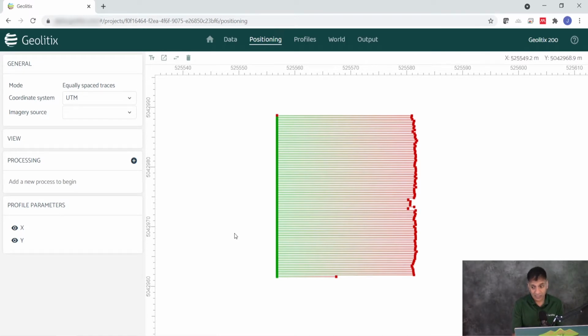And that's not to speak of all the GPS functionalities. And when you incorporate GPS, I mean, it's obviously a faster way of doing things than a traditional grid, but it opens up a can of worms when it comes to filtering out bad points or dealing with latency, which people tend to ignore for some reason. That's time latency. There's also the offsets between the GPS antenna and the center point of your data set.